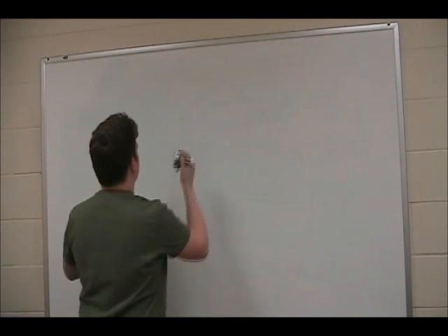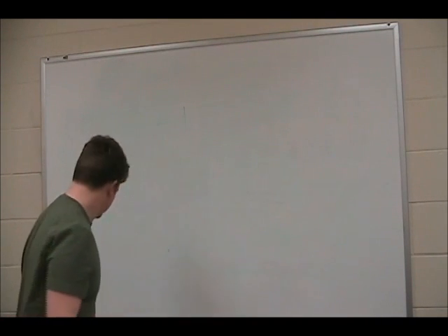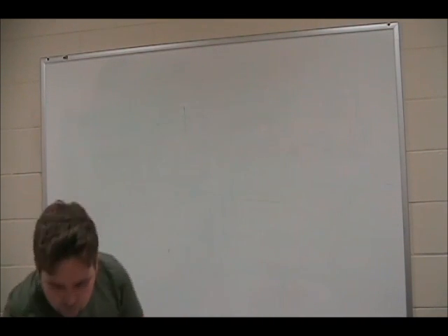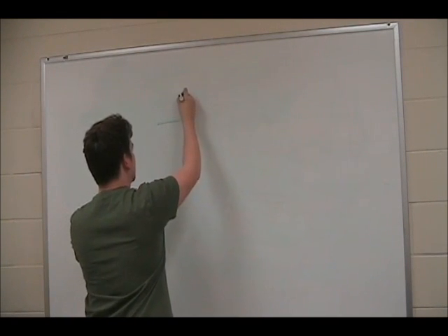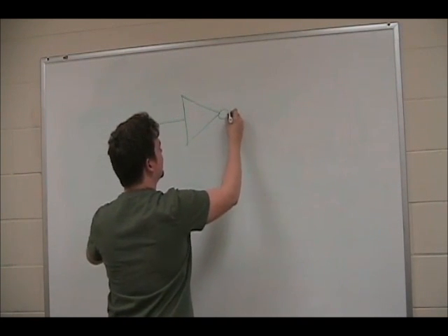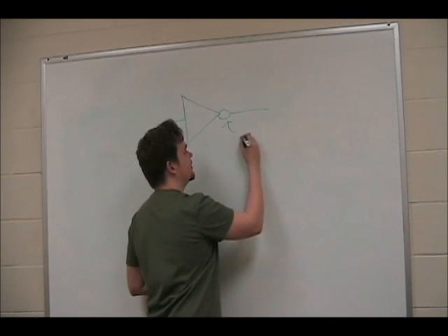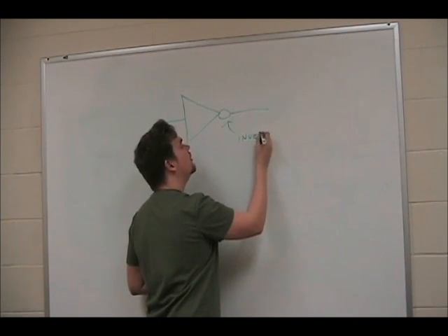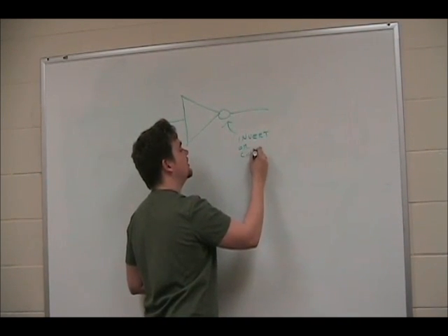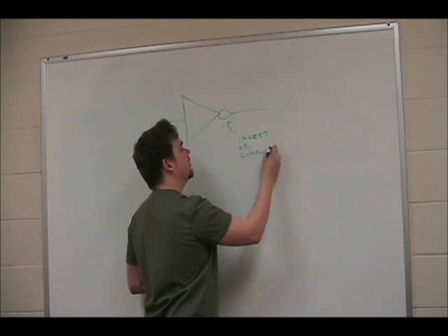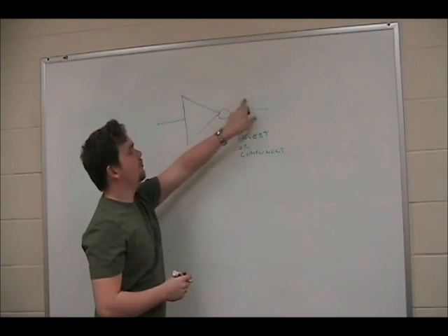First of all, we're going to talk about our truth table. We're going to look at our NOT gate again. Our triangle with circle on the end. Now keep in mind this circle, that little circle, means to invert, or to complement. Now what that means is that whatever digital signal is here, the output's going to do the exact opposite.